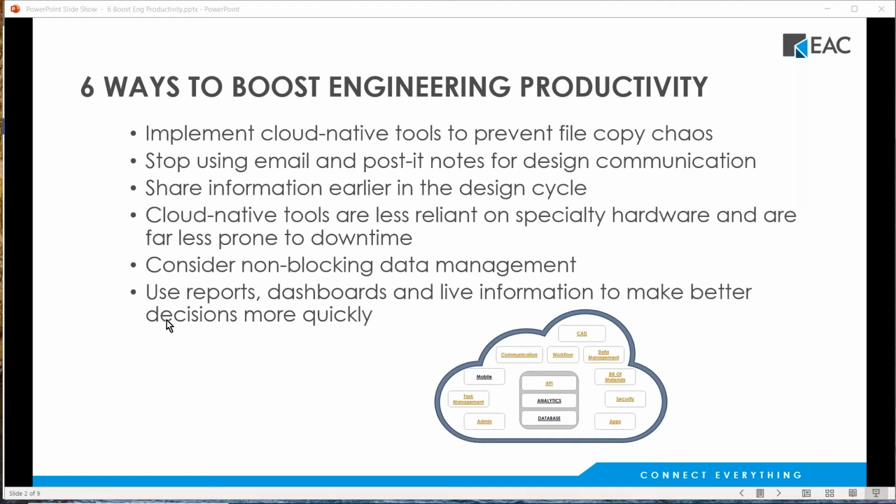The next thing we want to talk about is to consider non-blocking data management. And by non-blocking, I mean, if I take a file and I start working on it, maybe other people can see what I'm working on, but they can't change it as well. So they have to wait until I'm done, and then they get the latest version. Even if you're in a PDM or a PLM system, the exact same thing is true. We have to check things out. Once it's checked out, only the person who checked it out can make changes to it. The other people are just stuck working with an older version of that until it gets updated.